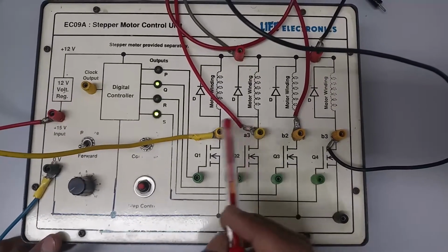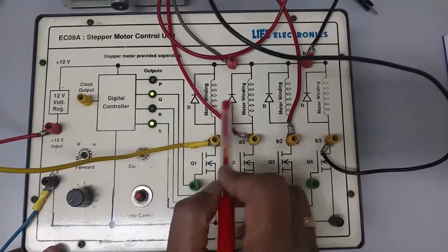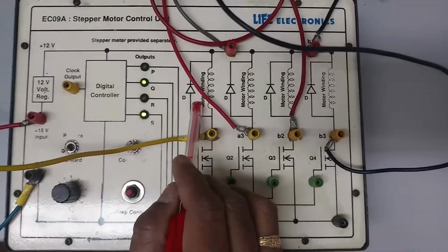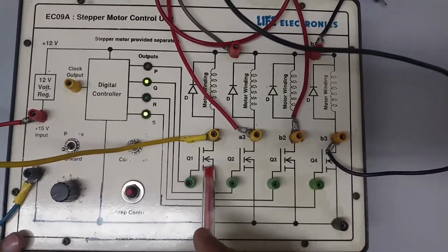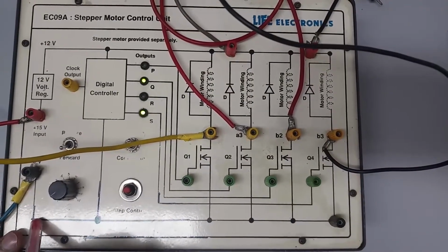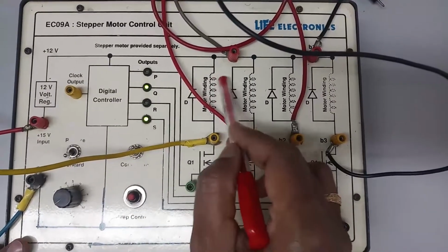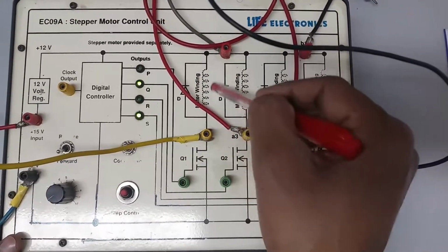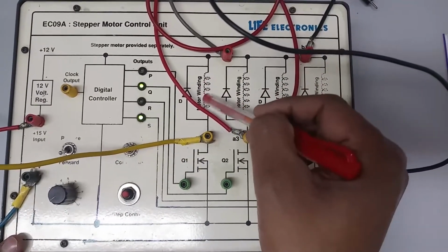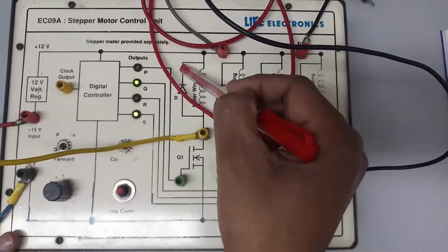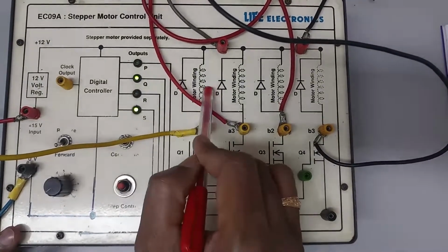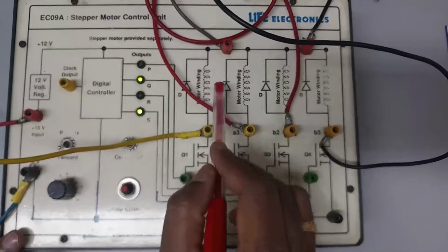Also, you can see here the motor windings, 4 windings are there. Across every winding, one diode is connected. The main reason for this diode connection is freewheeling operation. When the switch QN is closed, the current flows through the winding, through the switch, back to the supply. And when the switch is opened, whatever energy is available in the winding has to be freewheeled through this diode, so that the energy available in the winding will be dissipated in the resistance of the winding itself. So the coil has to be reset every time. For that, the diode is used. So that when the switch is in the on state, power is flowing through the winding, and the inductor coil will be energized.